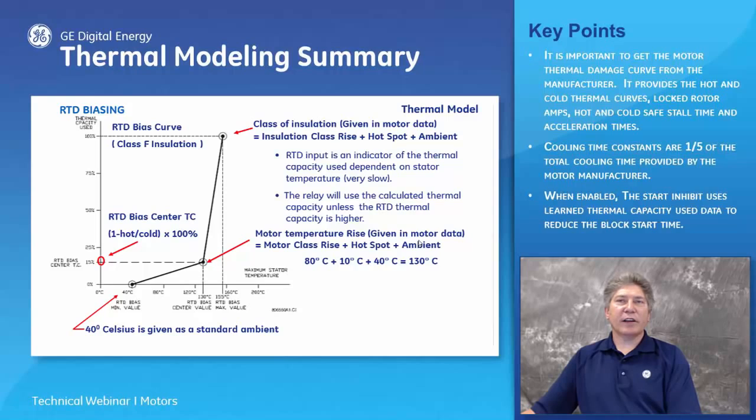If an RTD is failing, it could artificially force the thermal capacity used to an abnormal value, blocking the operator from restarting the motor. Verify that all the stated RTDs are within a few degrees of each other.